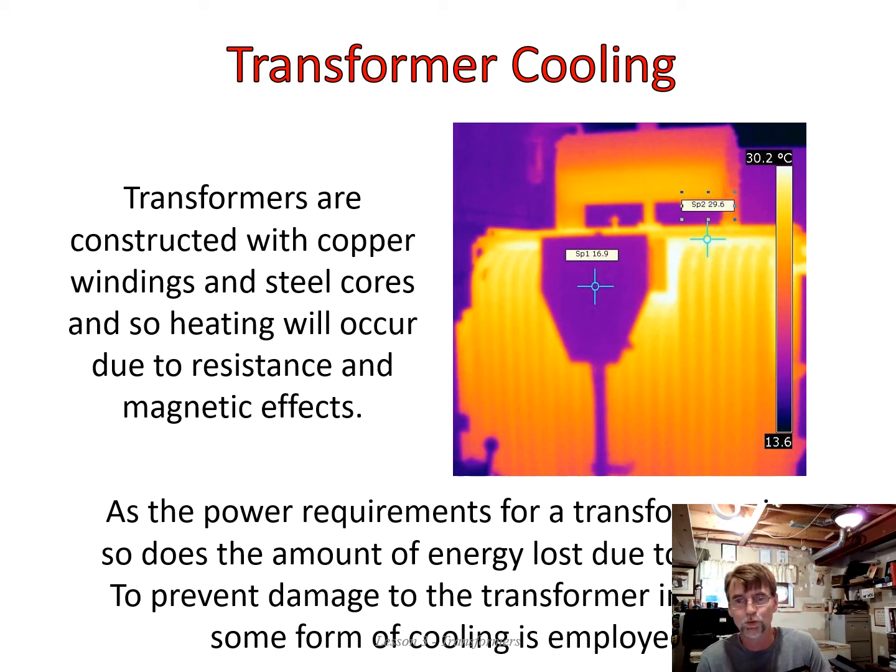some form of cooling must be employed. Wow, that was a mouthful. Sorry about that. Most transformers, the small ones, there's nothing extra offered in terms of cooling. It's kind of on its own. But as you increase the voltage and especially the current, you're generating more heat, and you need to take active steps to do something with that.